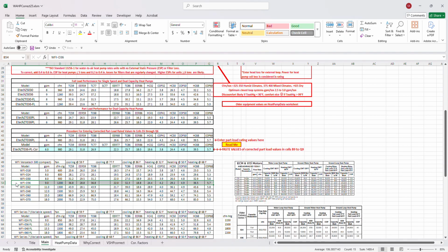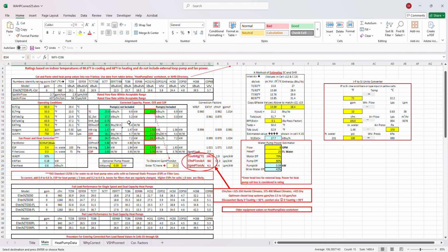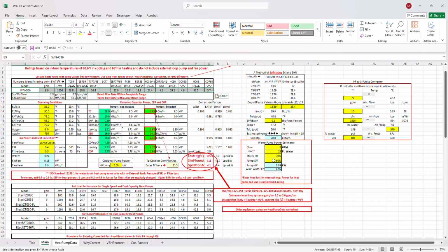So we'll go ahead and copy it, okay? And this is at full load, so we'll come back up here and we'll paste it in here, okay? So we're going to have to go back to the higher flow rates. We're going to change this. That's 28.9. So it's not a real strong 3-ton machine. Got us a good thing, but see here, we want to kick this CFM up to 1,000.